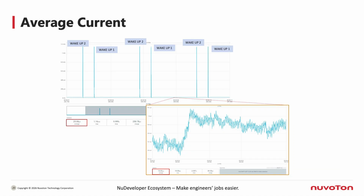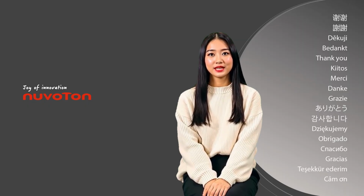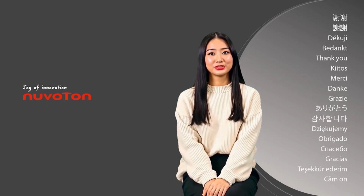Looking at the program flow, we can directly observe the system behavior during the current measurement. In the graph, the two peaks represent two CPU wake-ups, which correspond to the IFACNT values set to 40 and 10 in the code. This explains why the breathing LED blinks at different speeds. You can also try modifying the loop values in the main function to see how different settings affect the LED breathing pattern. That wraps up our introduction to the Low Power Timer PWM sample code in this training session.